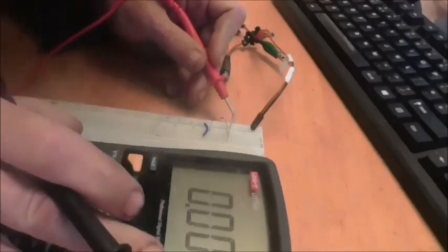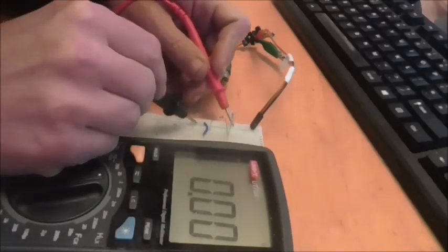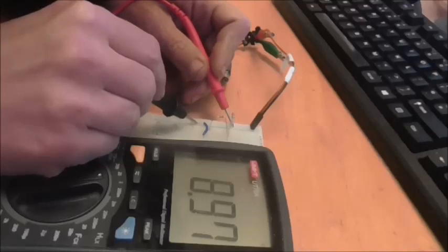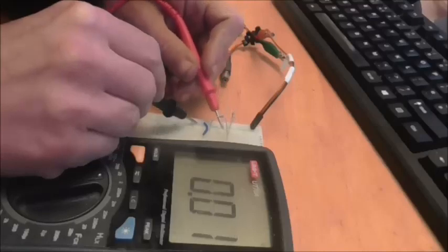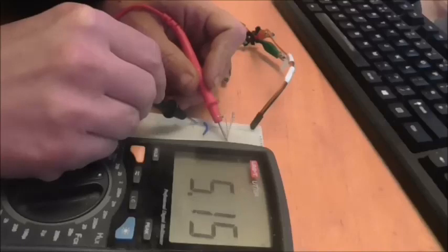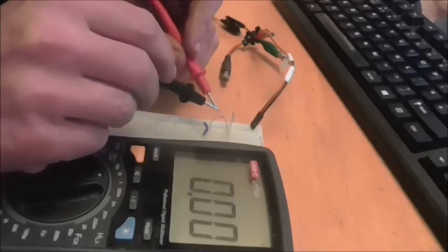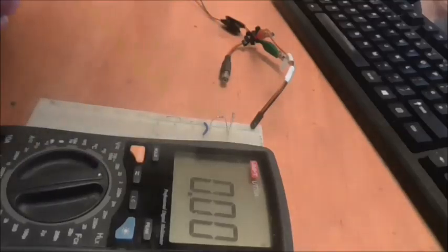Let me move the multimeter this way a little bit because it doesn't seem to be in the viewfinder very much. Try that again. There we are, we'll see it's not far short of 9 volts. A little bit, tiny little bit off. However, if I put this probe at the junction here, we should get about 5 volts, or more probably 5.1. And that's what this diode is doing. It's regulating a 9 volt supply and taking it down to 5.1.